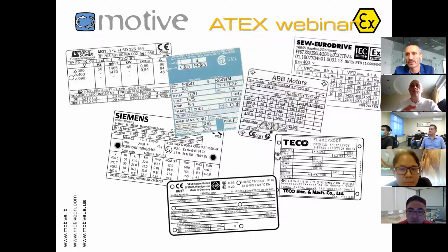Sometimes we also receive inquiries from people who do not know anything about ATEX or EX. ATEX is more the European way of calling EX. And they don't know what they really want. They just say, please give us the same. Maybe that motor, that gearbox, that drive was the wrong one for them. Maybe they're spending more than what they really need. Maybe they're spending more and getting the wrong one, which is not solving their problem, because maybe their problem is gas, and they are buying something which is for dust, just to make an example.